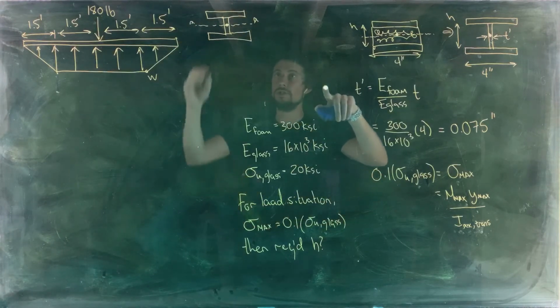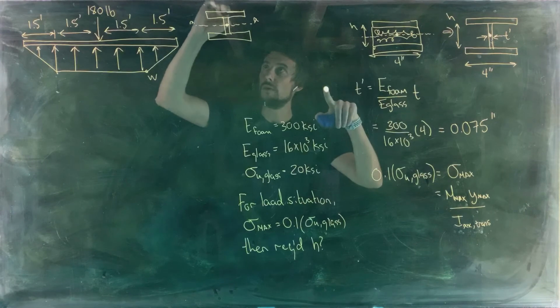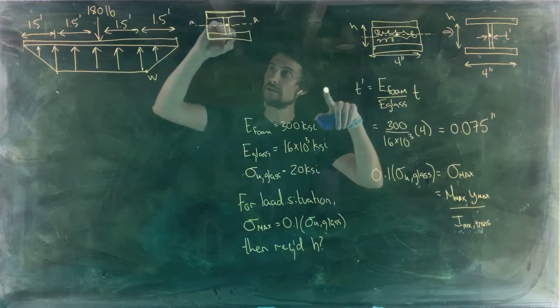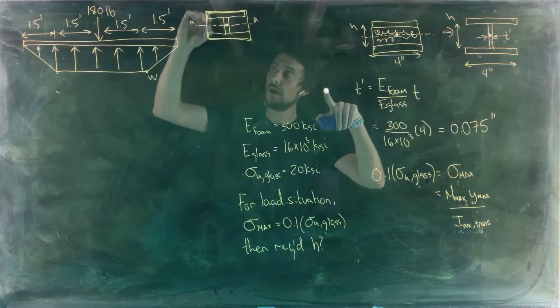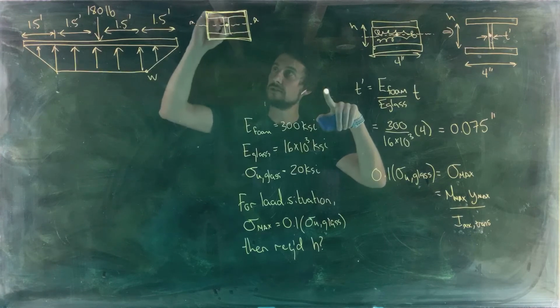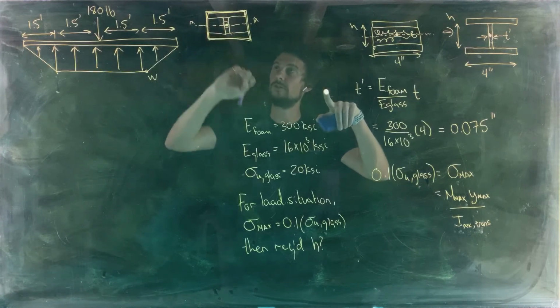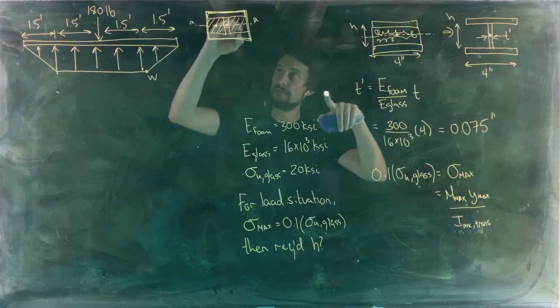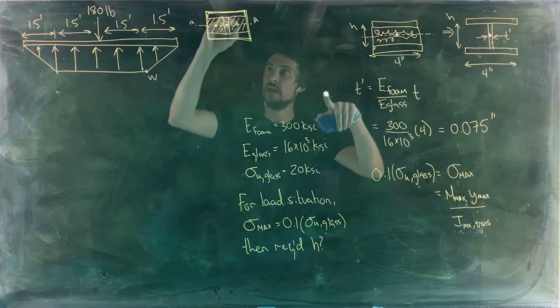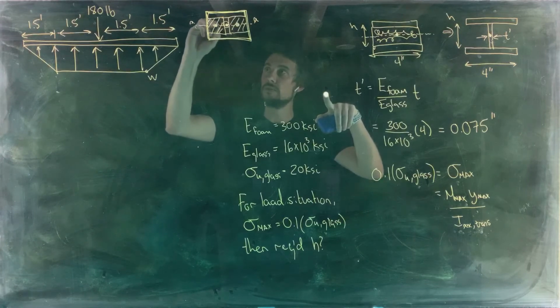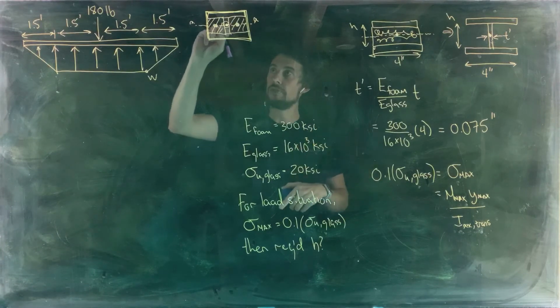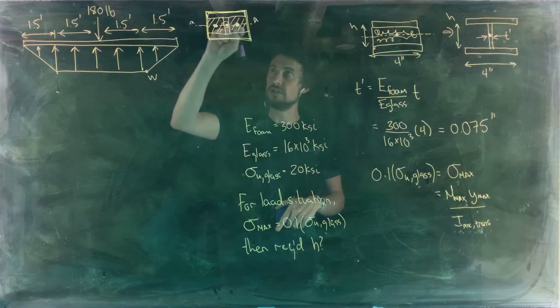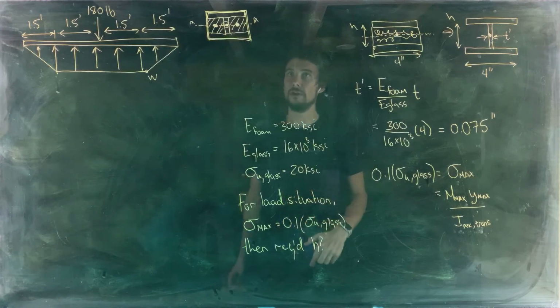Not difficult to do, because for an I-beam, we can do IXX for the whole outside here, and that has a centroid exactly equal to the centroid location for the I-beam, and then subtract off the values of I for the two gap regions. We can do the super simple position there because all three of those centroids that we're dealing with lie along the same axis.